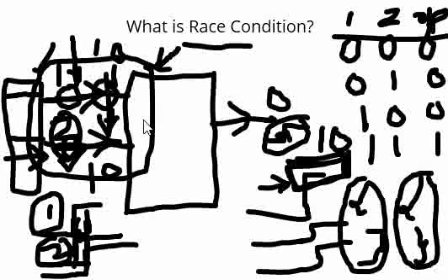These race conditions normally happen without getting noticed, and only once it occurs we get to know that there is a problem. So designers need to keep this as one of the checklist items to ensure that there is no race condition existing in the circuit, so that this can be a preventive action rather than a corrective action.